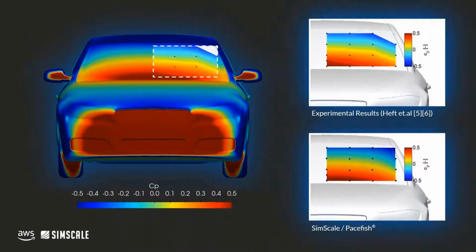The pressure coefficient, mapped across the front windshield, shows the variation in flow, from stagnation at the bonnet to acceleration at the A-pillars. The visual data shown is a comparison between the simulated results and the experimental results. The experimental results, measured at several discrete probe points, are shown with a linear interpolation. Taking this into account, the simulation results almost perfectly match the measured experimental values.